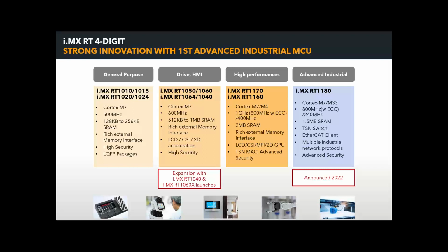And we take the MCUs to another level by adding MIPI, CSI, DSI, and also even a 2D GPU. So providing a lot of high performance graphic capabilities and camera interface capabilities. Also things like the time sensitive network MAC to do high speed Ethernet connectivity.